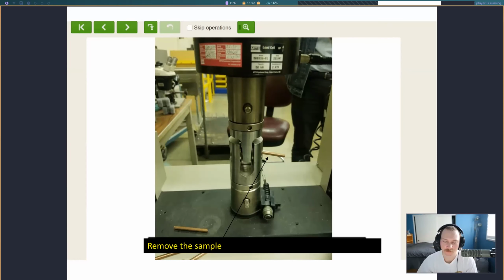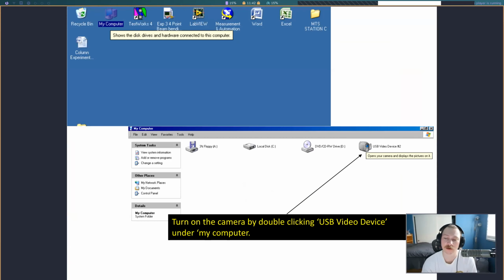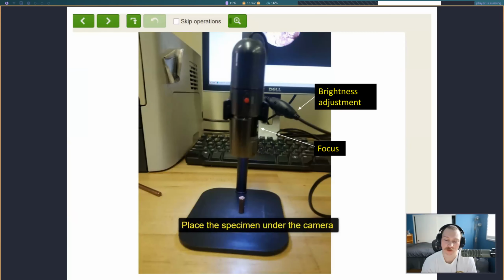So this part and this part here, they should both fall off, but sometimes it gets kind of stuck like this part here. It is totally sheared, but it kind of got stuck in this part here. So you're going to remove those, and then you'll get the very center portion here and record that length once we're done, to basically use that to calculate the bearing stress in the end.